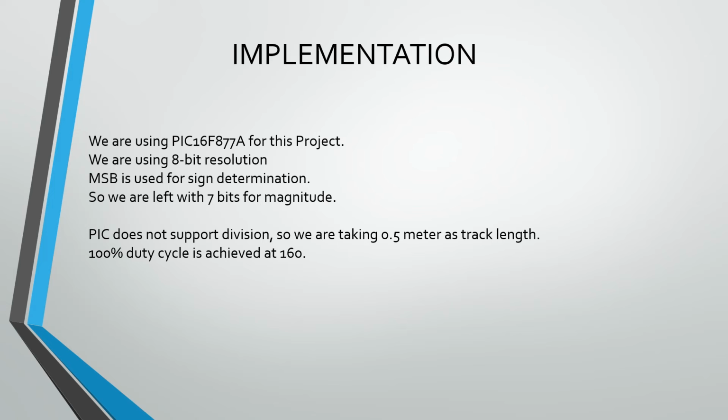In PIC16F877A for this project, we are using 8-bit resolution. Although it supports 10-bit ADC, calculations are easy in 8-bit. MSB is used for sign determination, like for positive velocity or negative velocity, and so we are left with only 7 bits for magnitude. PIC does not support division.